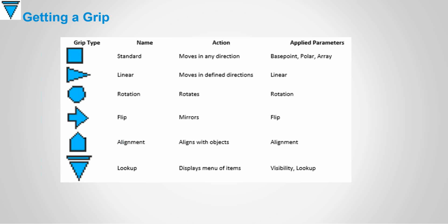And we can also create what are called lookup tables. And these are just basically pull-down menus for a particular block. And you'll see all this in an example. I'm not going to cover every one of these actions and parameters. We'd spend a week doing that. But I will show a couple of examples which will give you a good glossy overview of how to create the dynamic block, how to assign a parameter, apply an action to that parameter, and make it all work.